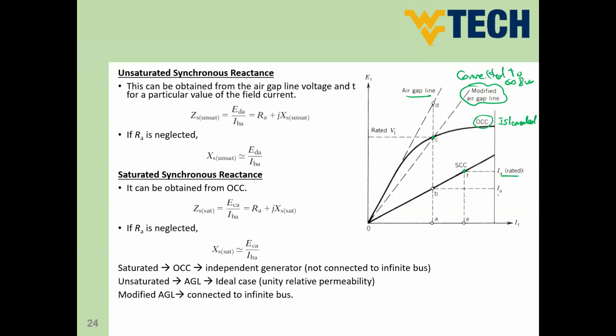You can make it at lower values, no problem. If you would like to test at lower than the rated current, this is okay, because as we mentioned, the relation is linear. So whatever the value you have, it has to be at most the rated value, but you can have lower values as well. This is no problem because you have a linear characteristic.